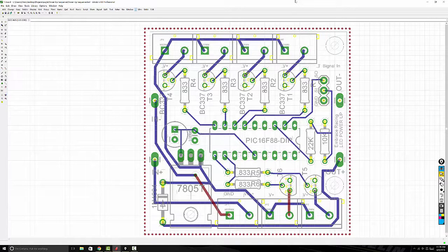And you have these two in Eagle. You should have these two things open, the schematic and the board, at the same time every time. Do not open one without opening the other. It will break the link between the two, and you'll get some sort of weird error in Eagle. And of course, you don't want to sever the link between the two because they're connected. I'm going to show you guys that also in a moment.